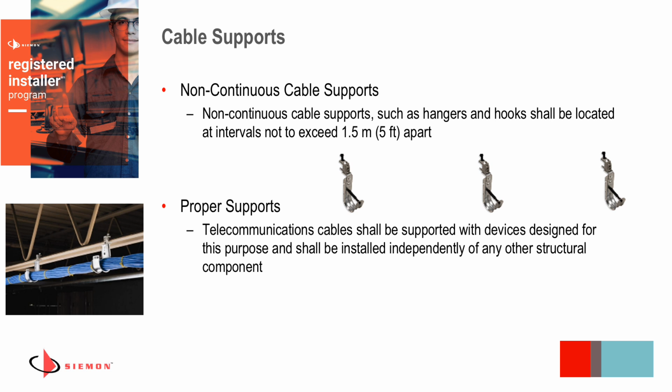Now, when you're installing those or any telecommunications conveyance systems, it's important to note that you need to support those independently of any other structure or component. So you don't want to be attaching those to something that may move or change over time. So you're thinking about things like the red iron, or using threaded rod or something suspended from the above ceiling to ensure that the pathways are dedicated for telecommunications use only.